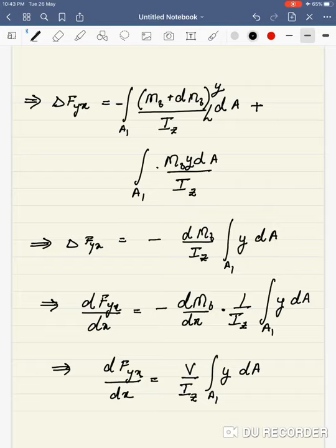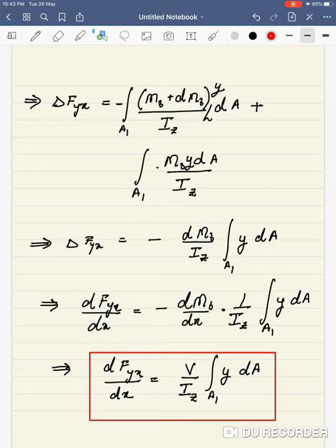We'll simplify this a little bit further, but this equation is important. Okay. It just comes from force balance. Obviously, you can imagine that this is going to be related to the shear stress. We don't have it exactly in that particular form yet, but it is. You can almost see that this is going to be related to the shear stress. It is not yet a stress because it's force by a length. If you have one more term here which makes it force by area, you will end up with a shear stress, right? Okay.